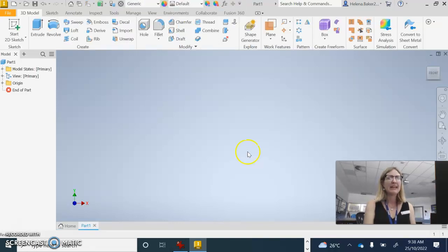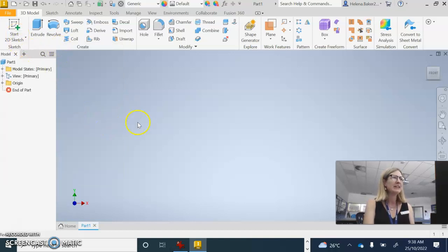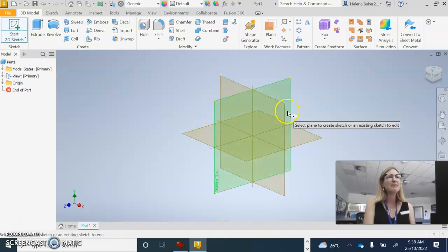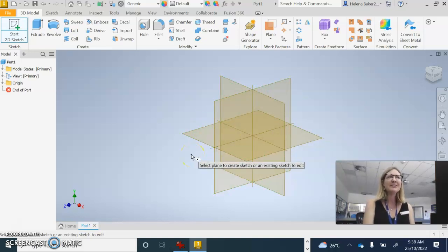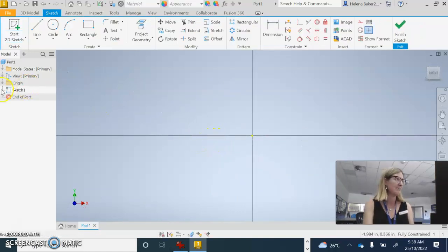All right. Now, the other thing to be aware of in Inventor is that we start with 2-dimensional sketches and then we add the 3rd dimension by extruding. So you guys are going to start a new 2D sketch. And really, it doesn't matter which frame you pick because when we work in the assembly, we can correct it. But if you have some awareness of what X, Y, or Z frame the part that you're modelling would sit on, you can do that. So I'm going to do it on this XY plane for the glasses frame.